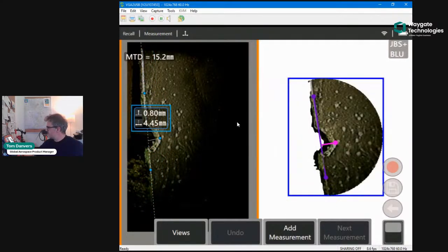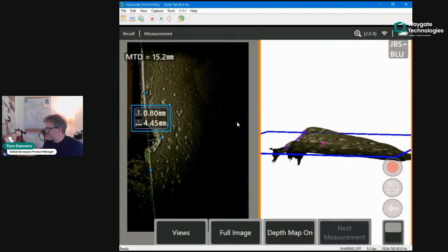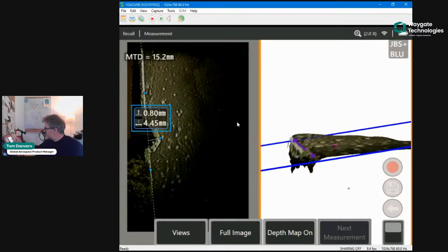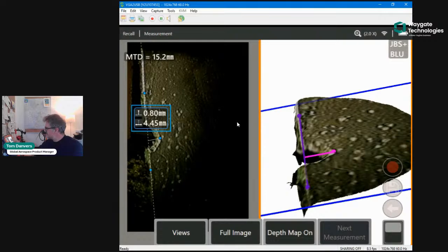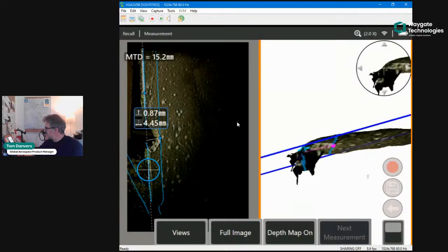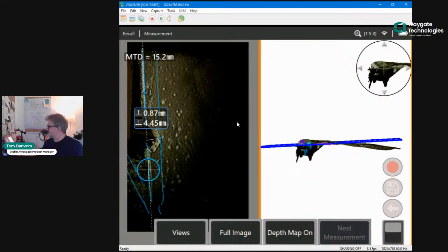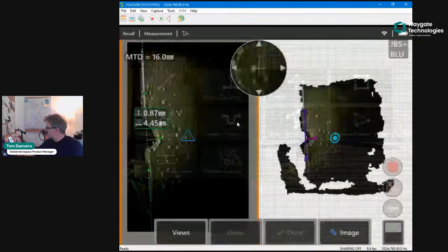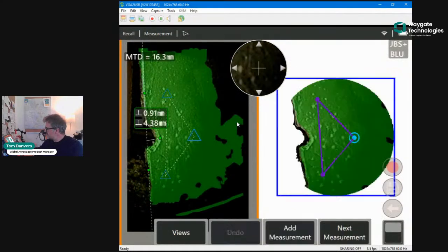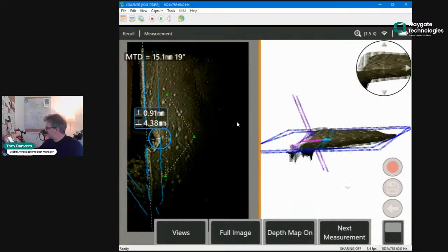Quickly able to drop 3 points on the edge of there. Checking my point cloud. Always check your point cloud. Always. Here's an example where I might choose to apply a measurement plane, especially if I force my cursors and make them slightly diagonal. So the measurement plane represented by the blue box doesn't align with the blade. So if I add a measurement plane to it, it'll force my points to now drop onto the measurement plane. So it's now a flat surface.